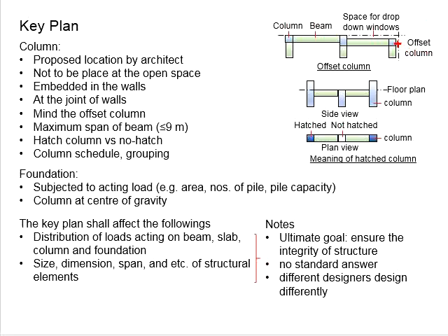Let's say now you are dealing with the first floor beam here, and you have a continuous window from the ground floor stretching into the first floor. In this case, you will need to allocate space here, which is equivalent to the minimum width of the brick wall, somewhere about 115 to 125 mm, which is just nice for the width of the window frame.